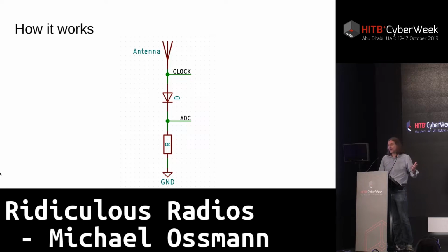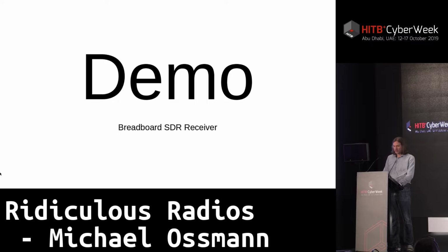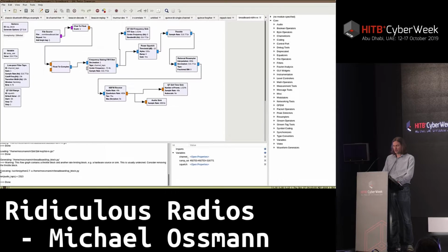And it happens to have a way to actually produce an external clock output from one of those internal clock generators. So we're using its clock generator, we're using its analog to digital converter, and we're then using its USB interface to take those samples from the ADC and pump them over to a host computer. And on the host computer, I run a flow graph in GNU Radio. This is GNU Radio Companion, which is a graphical interface to GNU Radio. GNU Radio is a framework for creating software-defined radio applications.